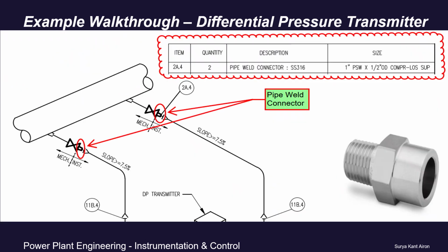So first, to fit into the above mentioned primary isolation valve socket, we need a process connector. A process connection could be flanged, threaded, or socket weld. In this example, as the pressure is high, socket weld is preferred over the threaded connection to avoid leakages. Thus, the above primary isolation valve is also purchased with the compatible provision.